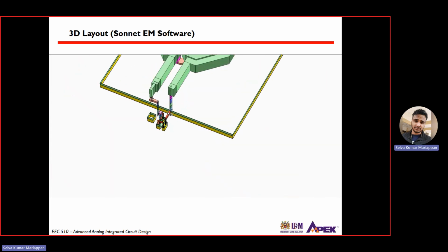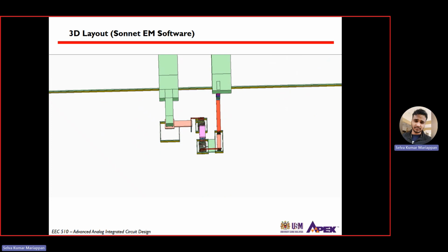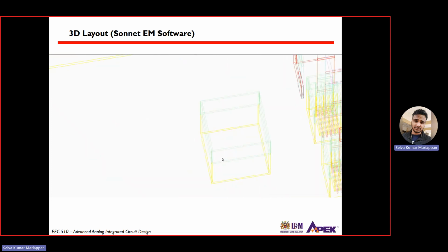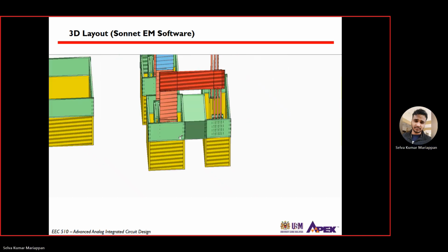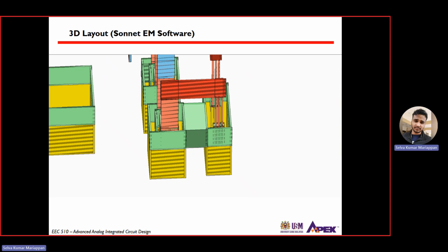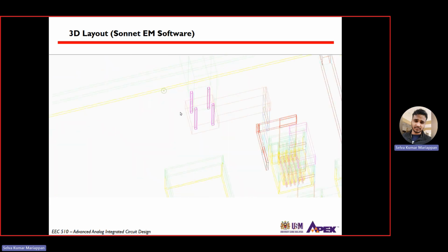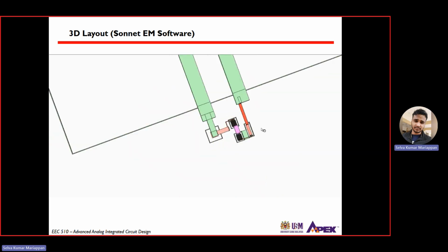Okay. So it is not on the same layers. One is on the top, one is on the bottom. And when you put a via, look how it's connected. So let's say you have a metal 1 in between and you want to bypass that metal. How do you do that? You just go through a metal 2, the top, and you do a bridge.